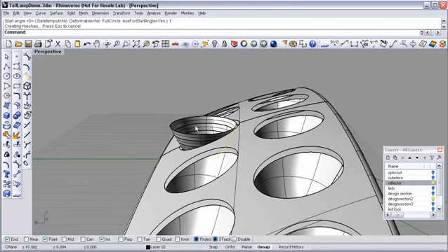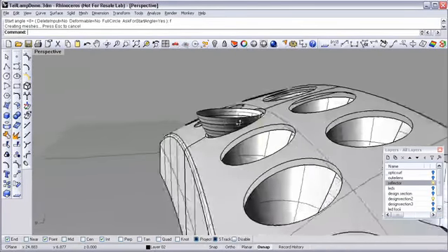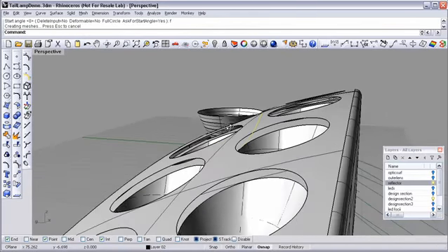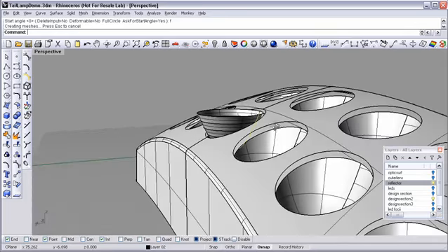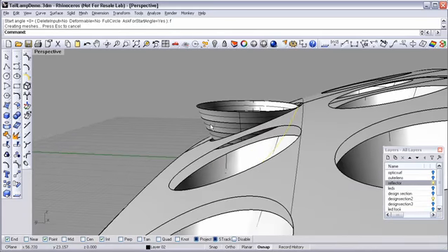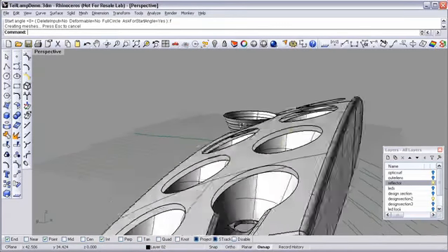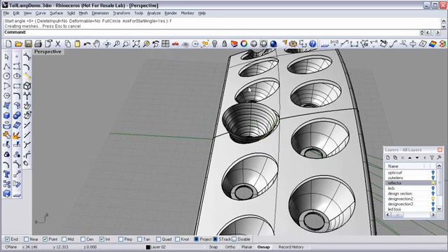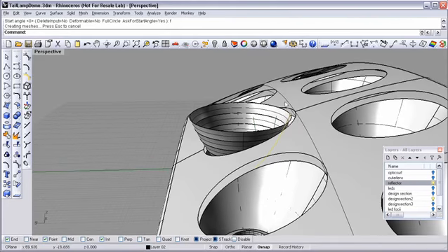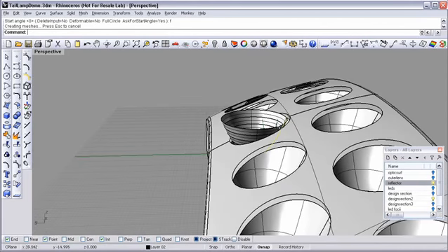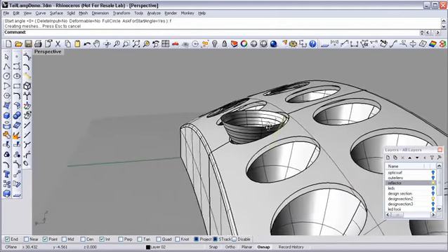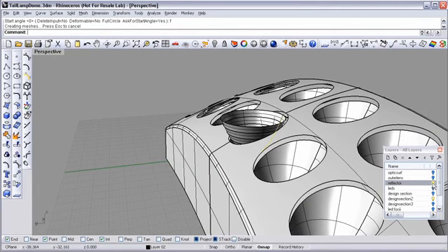One of the reasons that we work in CAD, and I'm working in the Rhino 3D package, is that you could work in any CAD package such as SolidWorks, CATIA, IGES, any of those packages are acceptable to do this in. One of the reasons that we do that is because we're able to take the customer's data, and we can manipulate our optics to interface with the data so that the optics that we're simulating are directly usable inside the part design.